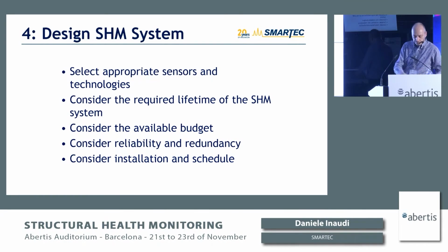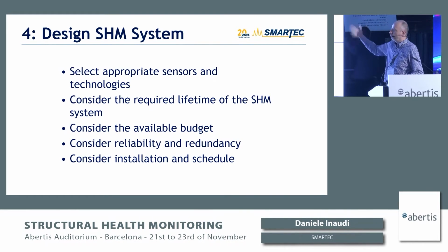So this brings us to point number 4, the design of the structural monitoring system. And I'd like to point out this is only step number 4. I've seen cases where this is step number 1. Someone says, oh, I want to monitor a bridge, let's put in a list of sensors. But if you don't do the analysis before, you might install something that works perfectly, but it's not useful.